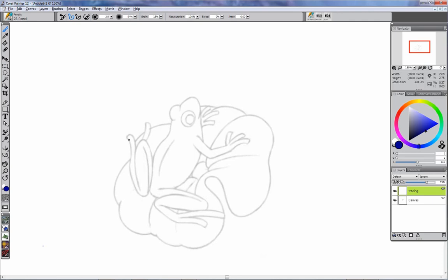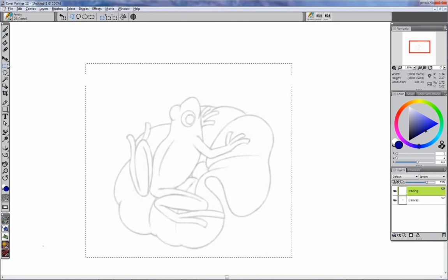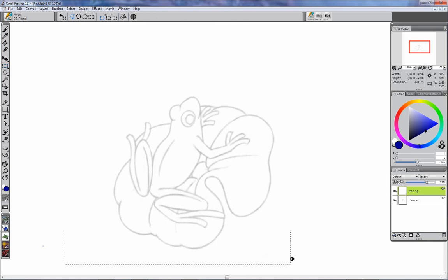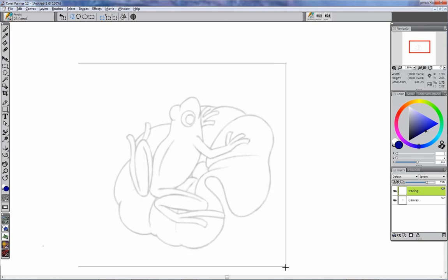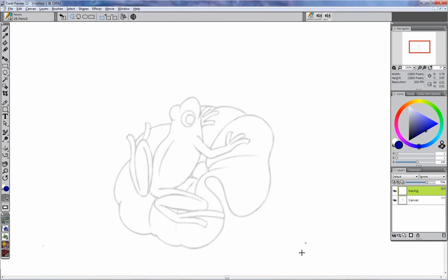By the way, remember to cut things, we just use select. That's this tool right here. You'll see I never reach over and do this. The reason I never do that is we have a shortcut for that, R. I just hit R, enter, and it gives me the same tool. In fact, I shouldn't have to even hit R, enter, I should be able to just hit the key R, and it'll give it to me.